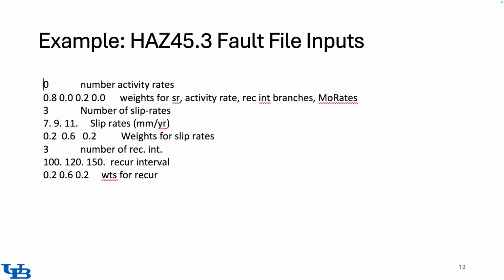And again, instead of assuming that we have fully defined the rupture, so it's not allowed to move, we will define the distribution for where the rupture is located, and so the distance will be calculated internally to evaluate the ground motion model.